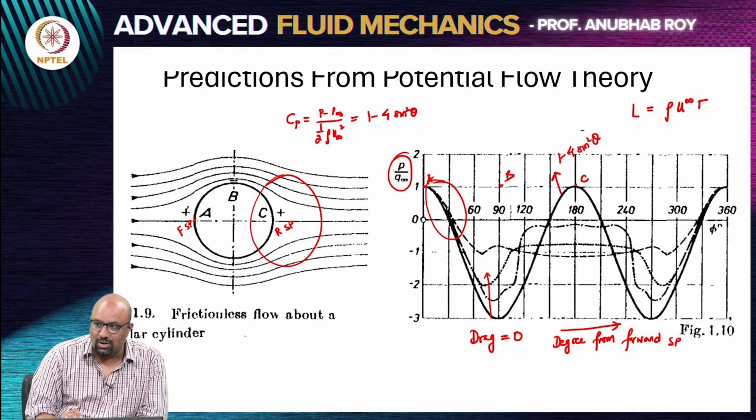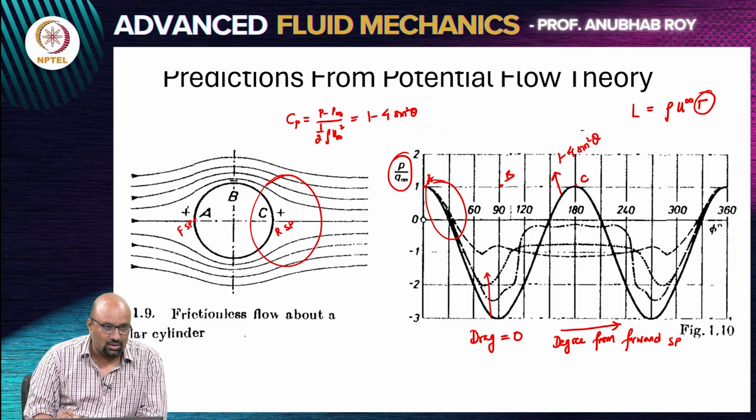It does not matter what is the shape of the object. So, for a 2D flow, potential flow past any object, if there is a circulation, and there is a flow past an object, or the object is translating, either way it will be experiencing a lift force. And then we used the Zhukovsky hypothesis or the Kutta condition to decide the value of lift.